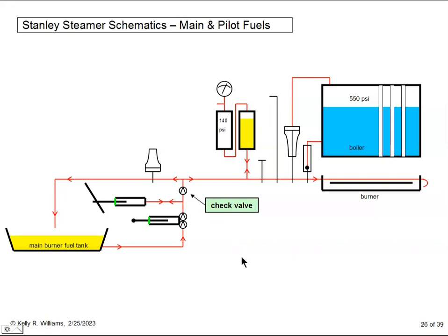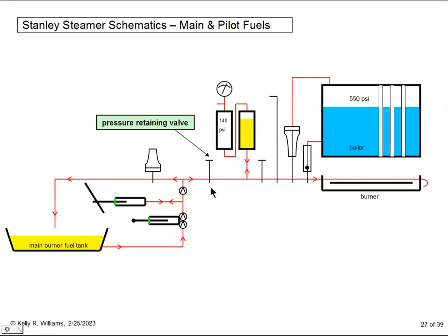And finally, unless all of these checks and the fuel automatic are seating perfectly, there is a risk that when the car is not moving, the 140 psi here in the tank will push all of its fuel back into the supply tank after a while. So we add this valve, called the pressure retaining valve, to isolate the pressure tanks from the entire supply system. When you park for lunch, if you close the pressure retaining valve, you should still have your 140 psi when you come back out to drive away.